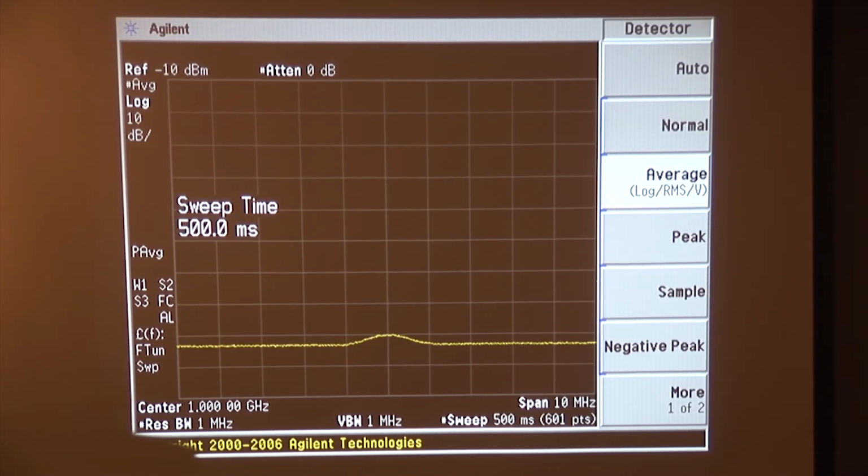So we'll momentarily disconnect the signal generator from the spectrum analyzer. We'll connect the signal generator to the input of the low-noise amplifier. The low-noise amplifier has to have a power source. It doesn't run on wishes. It likes to have about a 15-volt, okay, that's probably okay. Get that going here. Slightly cheesy clip lead connection for power, but all right. And now we'll hook up the output.